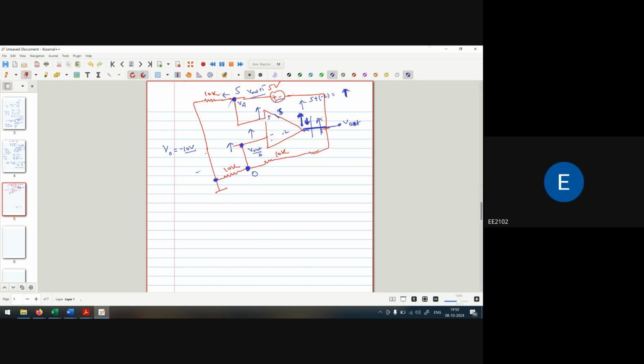One possible condition is if you are using this one as the minus and this one as the plus, then it may be possible that if we are connected as negative here and positive here, we are getting the lower voltage. Why? Because at this point the voltage will be subtracted, not added.